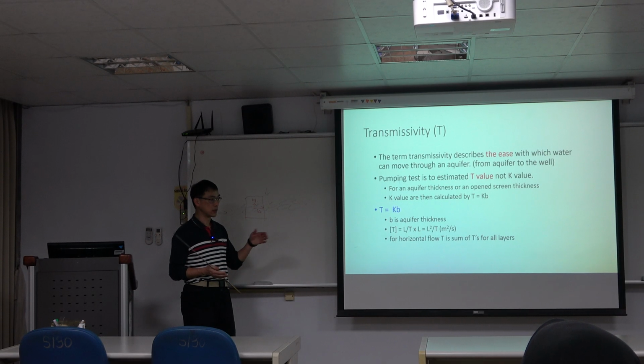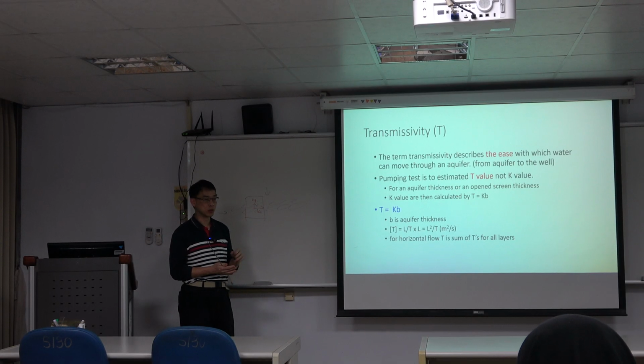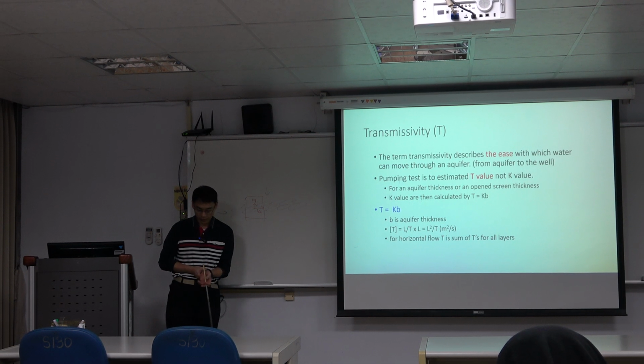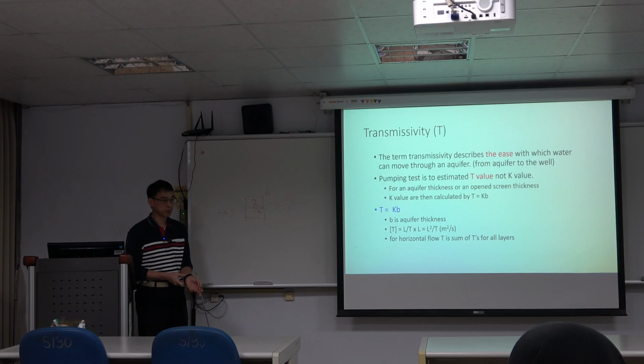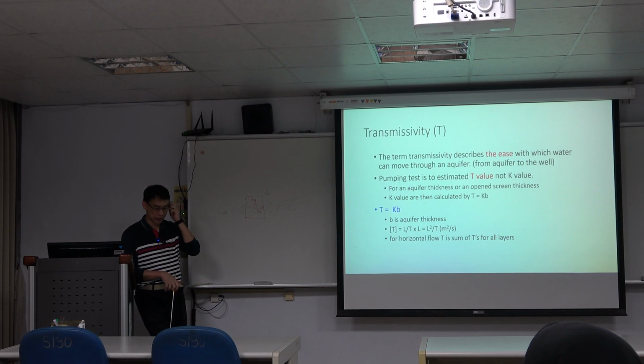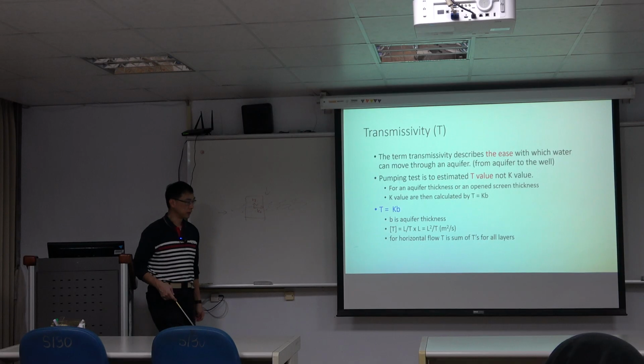Or if we use the T value, we should use the aquifer system to construct the whole numerical system, not using the materials for the assessment, and then you'll be able to put in the T values. But the T value becomes like an equivalent concept. How it can be used for the assessment is also not easy. So commonly we still go back to using the K values instead of the T values for the assessment.